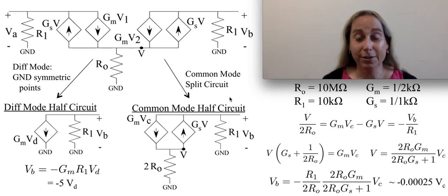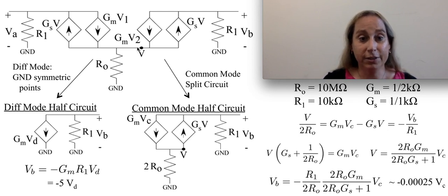about a particular sort of symmetric circuit that has dependent sources in it. Typically people don't go into too many of these conversations where you have both things, but it turns out it's a very rich set of concepts, and also a very rich structure in terms of how these typically get done. If you look at the circuit over here, for those who've done some advanced related circuits on this, you'll immediately realize this is a typical small signal model you might imagine for a typical differential pair amplifier.